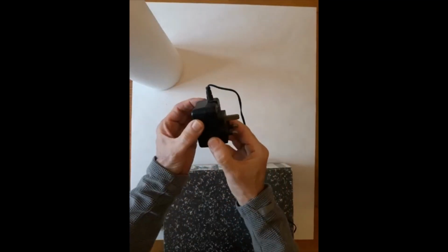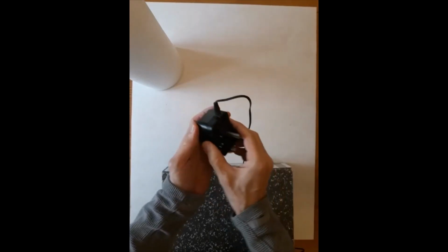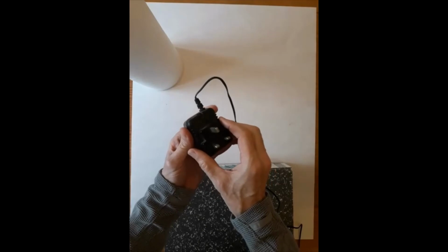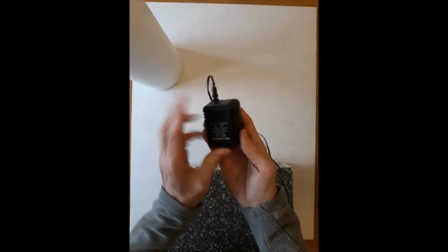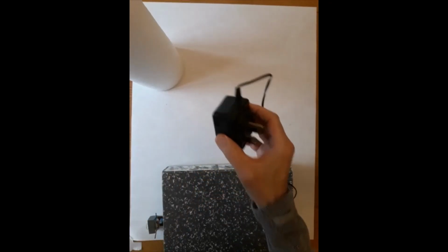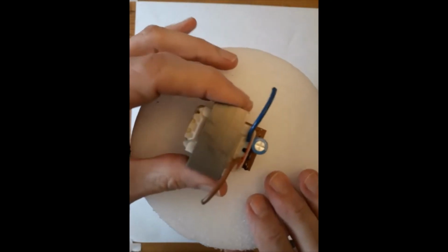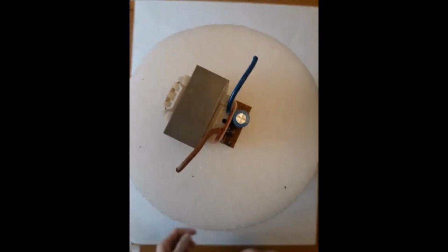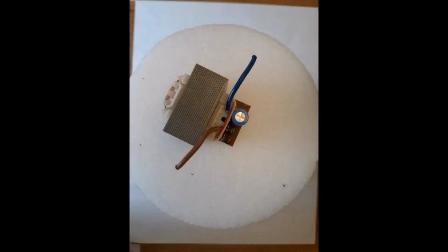So here is a plug-in power supply. This is used to feed the speakers, which are with my PC. So I'm sure you know the arrangement. Plug this into your 230 volt socket, and the output from this is 6 volts DC, and that supplies the speakers. So inside that particular casing is something that will look just like this or very similar. And what we have is a transformer and a bridge rectifier with a smoothing capacitor.